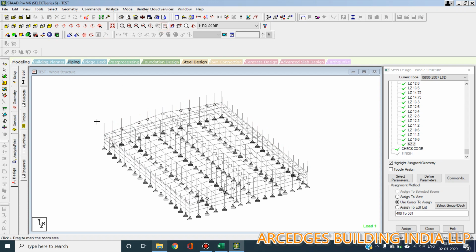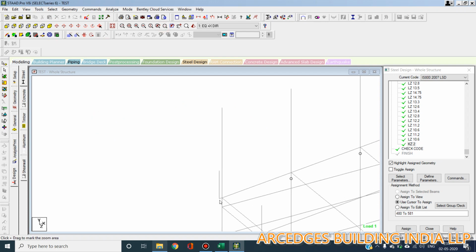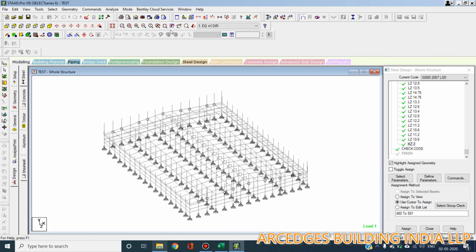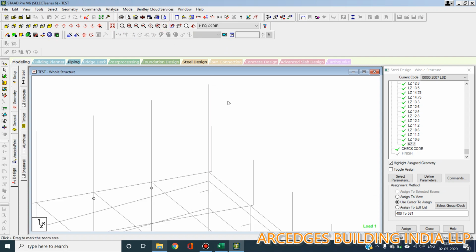If you zoom here, you will see that on the left hand side we had given 300 mm spacing. So the program has generated 300 mm spacing, and in the front fascia the program has taken the front fascia in line with the cladding. Now if we had generated both of these in line with the cladding, then only one of these two would have been there. The program will automatically take only one if we are generating all four sides as straight.